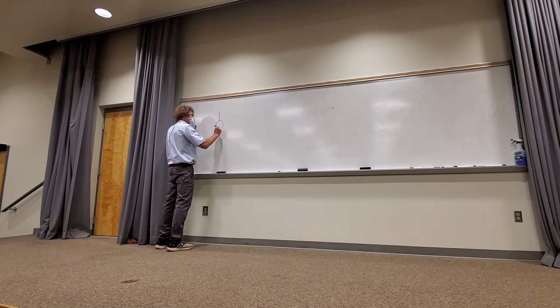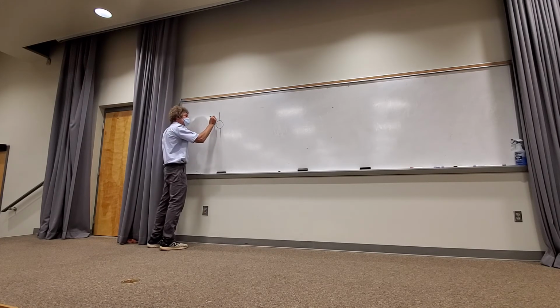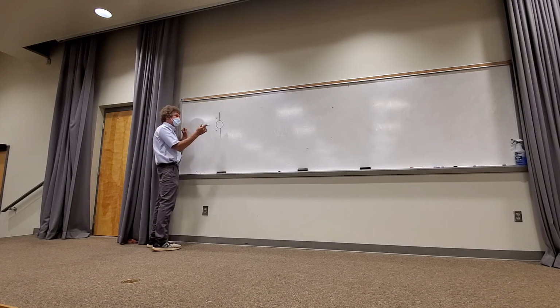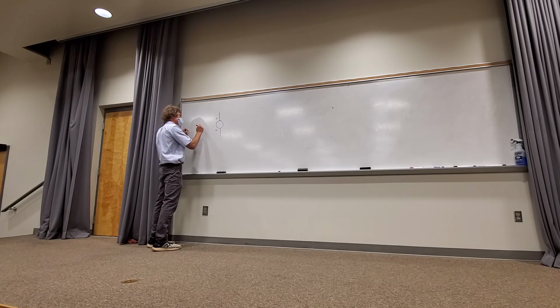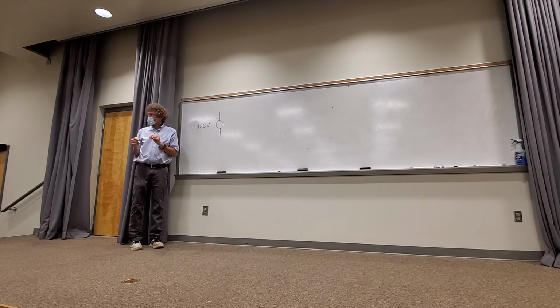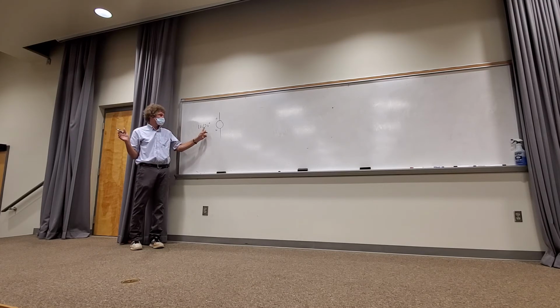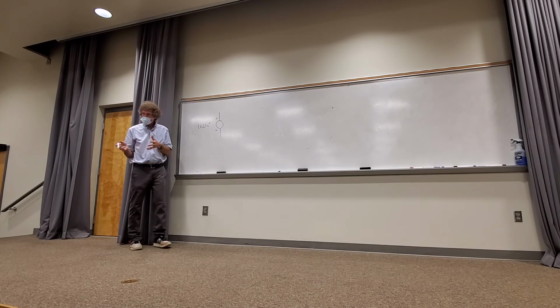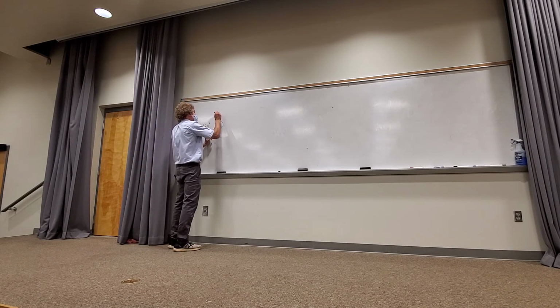Here, this is typical. They assume everything varies as cosine omega t. So right here, they might have 10 volts at an angle of 30 degrees. That's a voltage source. Do y'all follow me? We know it's in the phasor domain because this angle doesn't appear at constant DC voltages. This is a phasor form of a problem, really its interpretation.